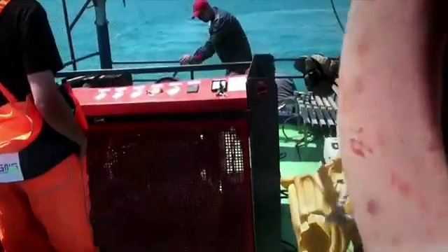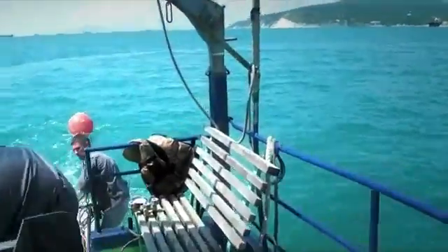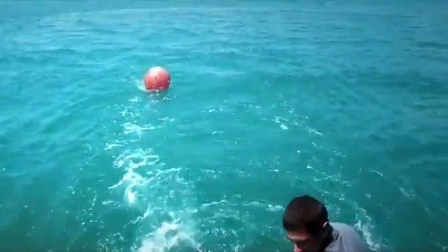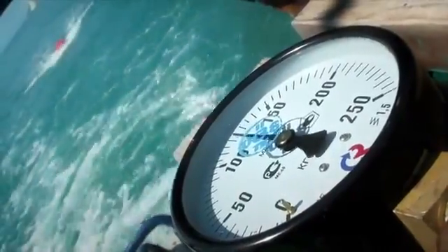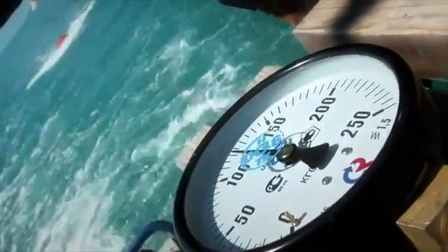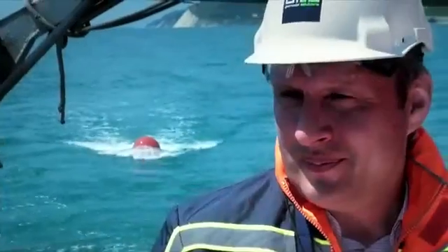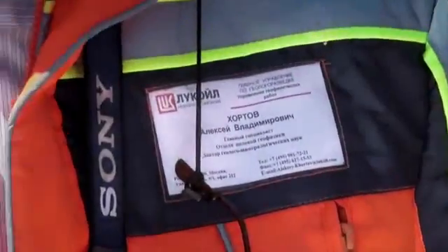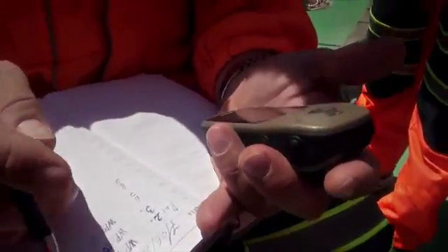Once the deployment of the nodes is completed, the second phase of the survey begins, shooting from the vessel with a seismic energy source. The air gun is submerged into the water and then it shoots, producing seismic waves by discharging the pressurized air into the water. The source vessel shoots along the survey lines. Survey shooting lines are set up into the navigational software according to the survey plan.